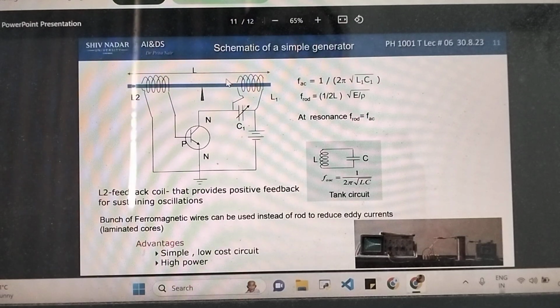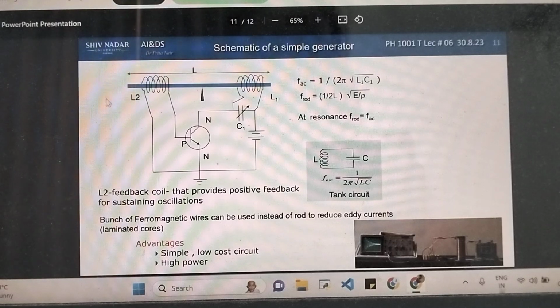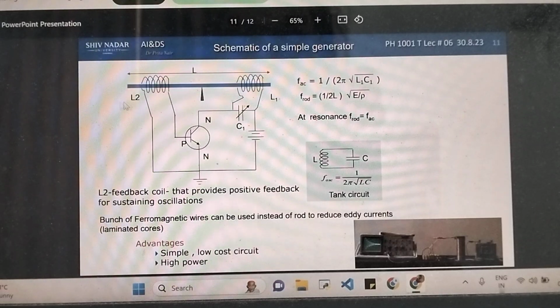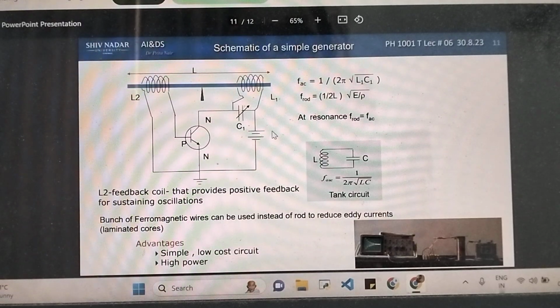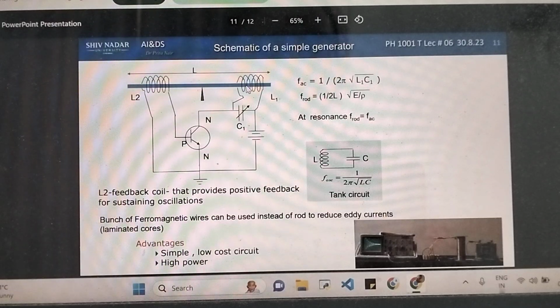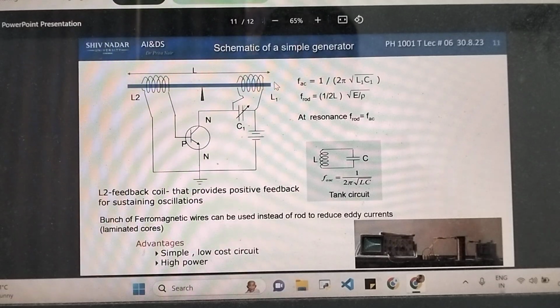Now this force causes the rod to elongate, as we saw. It pushes the air column around it, that leads to the generation of ultrasonic waves. So that is the basic principle. I'll repeat, this battery generates electricity which passes through this current carrying coil, and it is placed in a magnetic field. A force is exerted, elongation and compression happen of course, and it leads to vibration of the air column around your rod. That vibration leads to the generation of an ultrasonic wave.